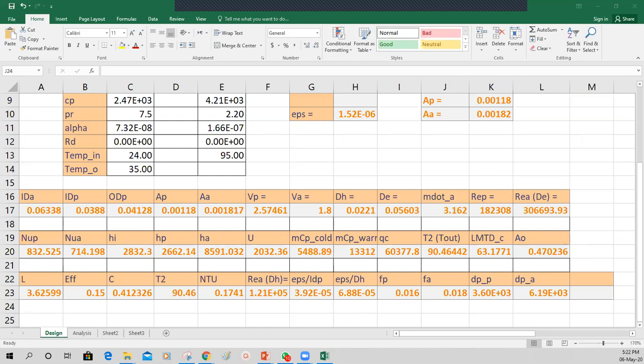Now this watt is to be converted into the boiler specification wattage, that is, what watt boiler do you need. But in the boiler there is no flow rate, only the tank size, only the capacity, maybe like 5 liter, 10 liter or 20 liter boiler, right? Let's say it is a 20-liter boiler, for example. So you only have mass, you do not have mass flow rate. So the mass multiplied by Cp and multiplied by dT, that is, what temperature rise you need, right? Clear?